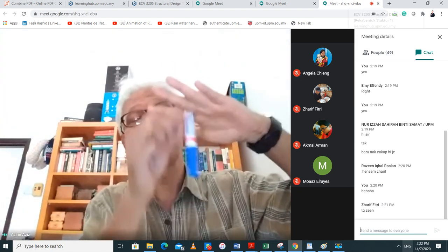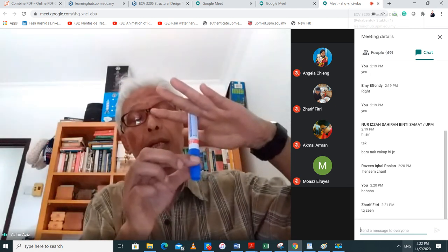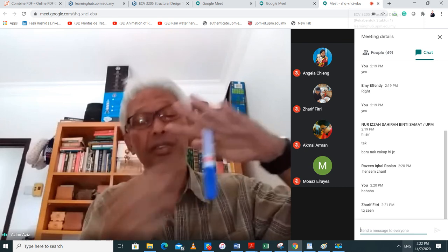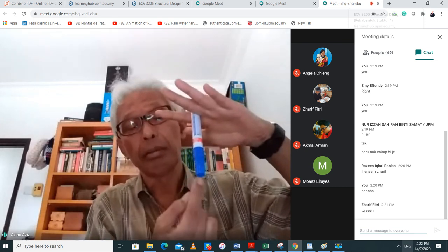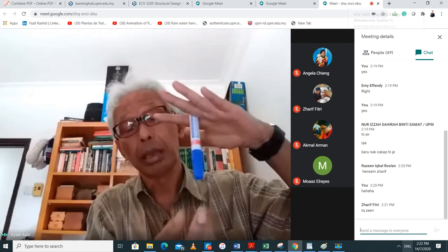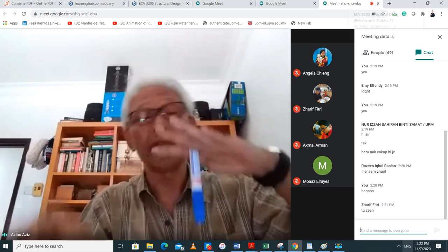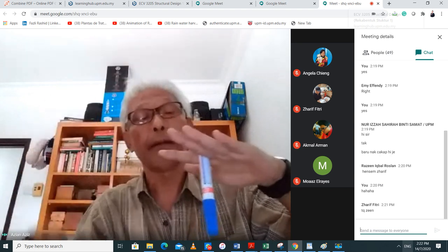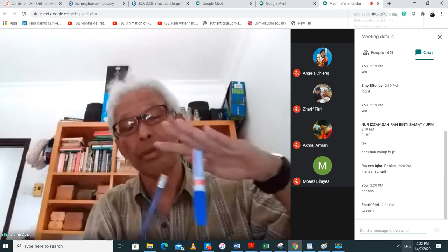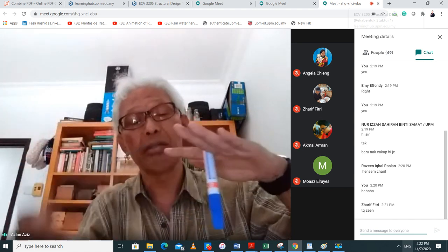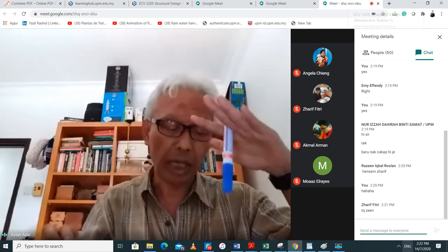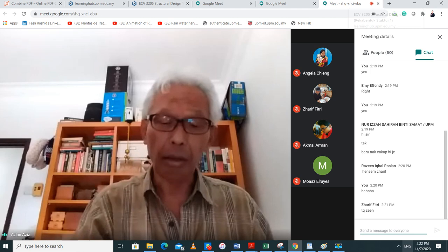So it's just the skin friction, which is a stress, multiplied by the surface area, plus the tip resistance at the bottom multiplied by the area of the tip. This is in relation to the load that you apply at the top, so there is a friction that reacts against the load, and the tip also reacts against it. That's why you get that equation on page 14.